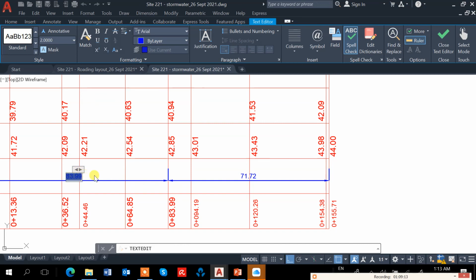I'm going to specify the slope as a gradient. I just put the gradient 1.61%, 450 mm PE, polyethylene pipe, or capital letters PE.